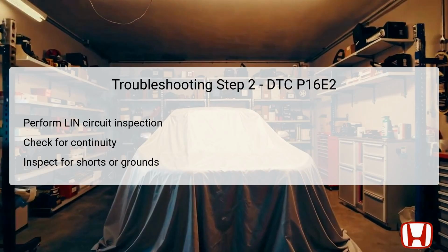The second step involves a detailed inspection of the LIN circuit, which is essential for transferring information between the alternator and the PCM.